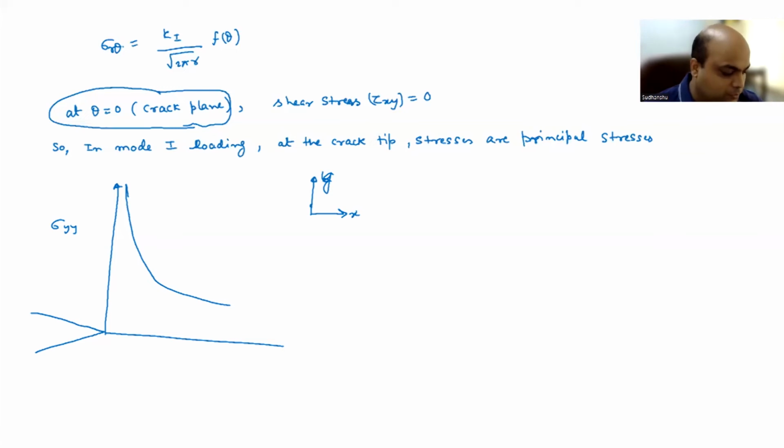So this is the nature of the stress distribution. It continuously goes down. Now, if you see, you have sigma xx also, sigma yy also. That means you can have stress triaxiality if you have sigma zz also, isn't it? We were talking about the plane stress condition, that's why we have sigma yy and sigma xx. So why are we getting stress triaxiality in the presence of a notch or crack? That question comes to mind now, and that is what we are going to discuss. So, stress triaxiality.